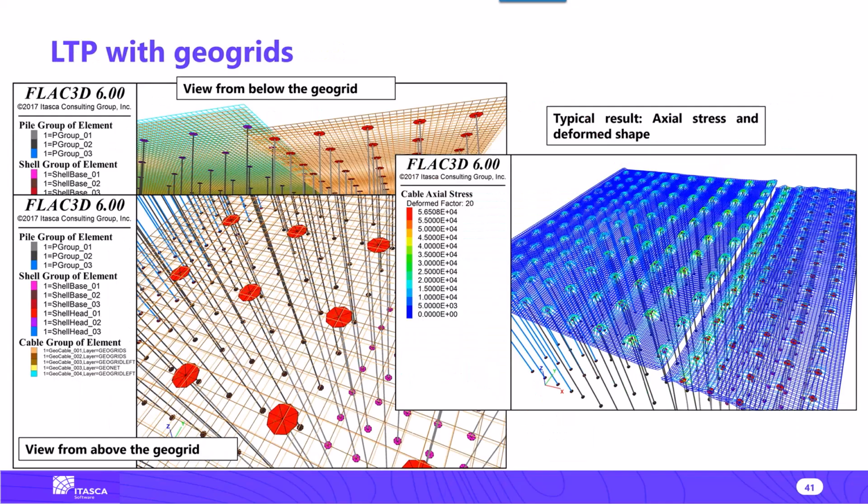Okay, so this is a picture that shows the detail of the column with the shell at the top that takes into account the physical size of the column itself. It is important in this type of application because if you just have a link at the top of the column, it tends to grab just one zone, and so you have a very concentrated stress. On top of that, if the zone is made of, let's say, a Mohr-Coulomb material, for example, it will yield at some point. So you would not be able to correctly capture the load transfer that happens at the top of the column and the arching that would happen naturally inside the embankment. That aspect would be completely missed.